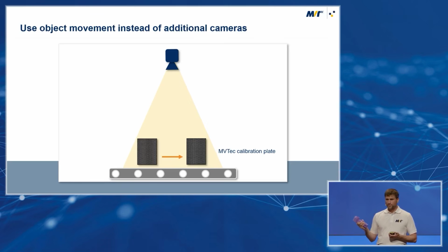In this case, we can see just 1 camera. But on the floor, this is a conveyor belt in this example. So having a feature like a moving part, like a conveyor belt, we look at our object. Here, we can calibrate with the calibration plate on the left side a position, and on the right side, another position. So we have 2 positions that are calibrated, and we know the velocity of the conveyor belt, because maybe we use an encoder, or in the real world it has constant velocity. So we know where the parts are, which distance they moved.